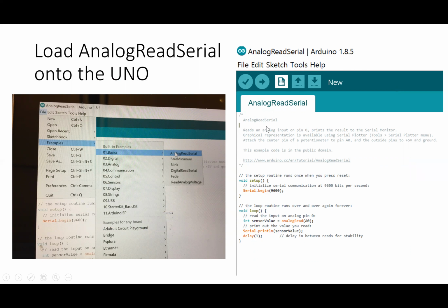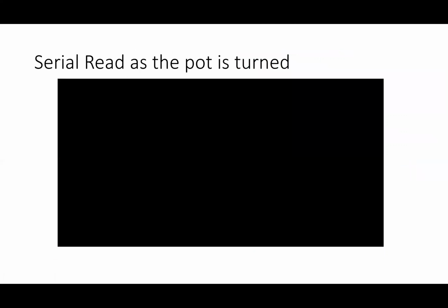Anyway, bring up this sketch, and then if you're confident your Arduino is connected, just press this arrow here to compile and load it. If for some reason it doesn't load, go to the Tools, Get Board Info, and see if it's talking to the board. If not, set the COM port on Tools. We discussed these problems in the first lecture in this series.